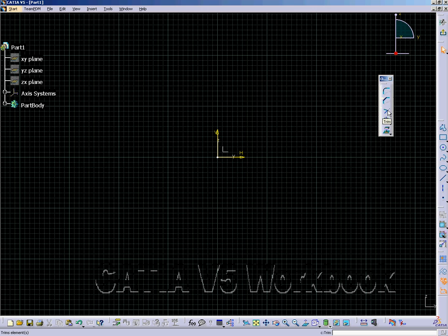Notice our trim has a little down arrow at the bottom right of that icon. If you drag your mouse over that down arrow, you'll get an arrow that shows up as a double arrow. If you click on that, it will give you the additional options to that trim tool. So any of these tool icons that have that little down arrow, you know there are additional options.